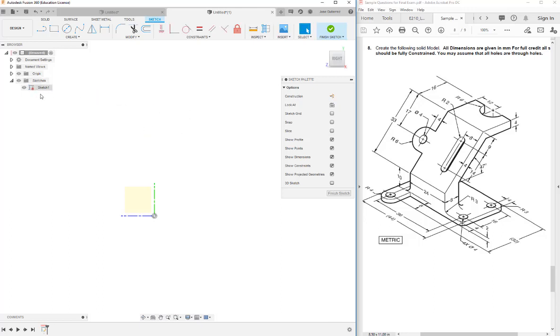And the easiest way is to make sure, as I go, it's mostly constrained. So the first line I'm going to create, with my origin right there, is this edge here, and I'm going to work my way around. Okay, and I've snapped it to the origin. Notice on my sketch palette over here, I am already allowing the snap constraints. I'm seeing this green dash and vertical line here, meaning that I'm getting a vertical constraint. I would like to do that.